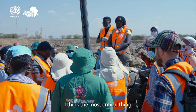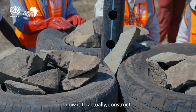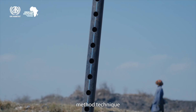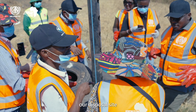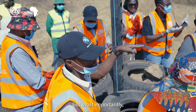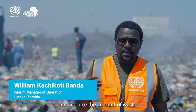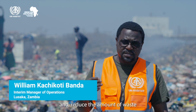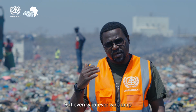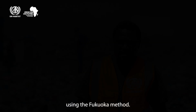I think the most critical thing that I take back home now is to actually construct a Fukuoka landfill method technique that will help stabilize our disposal site and ensure that we have a controlled waste system. But most importantly, to have gas emission pipes, leachate treatment, and reduce the amount of waste that goes to that particular cell so that we enhance the recycling. But even whatever we dump must be dumped in a proper way using the Fukuoka method.